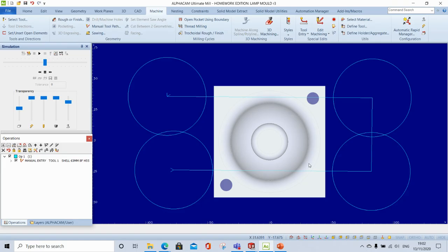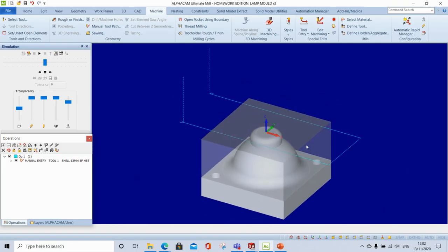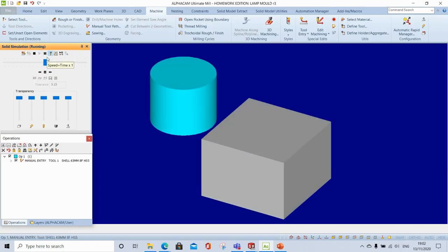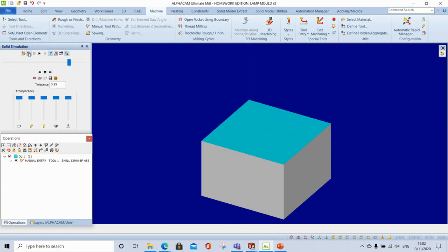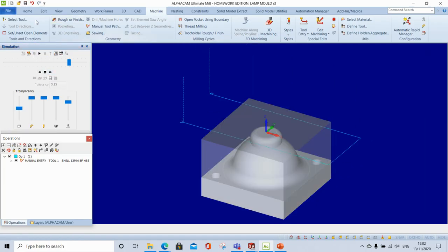That didn't work. Oh, there we go now. Press escape again. You can see we have a toolpath. If I go to simulation, I will see that it's taken 2 mil off the top as per what we would normally do. These are all going to be grayed out because we don't have any green geometry to pick, but what we do have available to us is 3D machining.